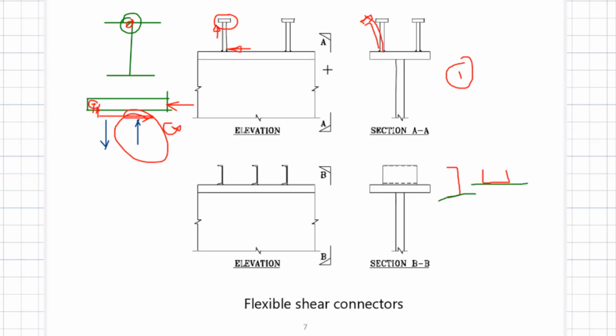That is why we say a very good shear connector should have an element which will stop the separation of the steel and concrete interface because of the moment equilibrium. Now, in the earlier case, I said this is no for me because there are no elements that are going to stop the separation of the concrete here. However, purely by friction of the surfaces, it is going to give. However, if I put a channel like this element, it is going to resist the upward separation, and it will also resist the shear.